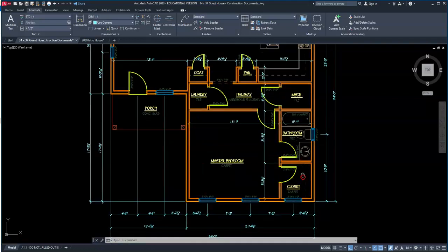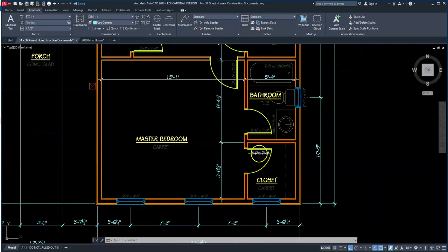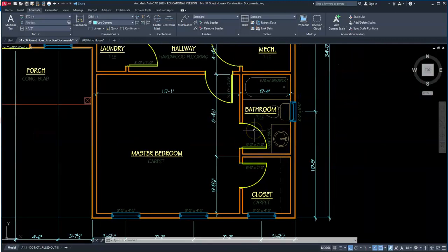Okay. Please note that the dimensions are on the bottom here. It's the left side of the wall if we were rotated around. Just keep that consistent throughout. You won't for this one, but you could choose the right side of each wall instead of the left. But let's keep that consistent on the left so your numbers match with what's on the floor plan.